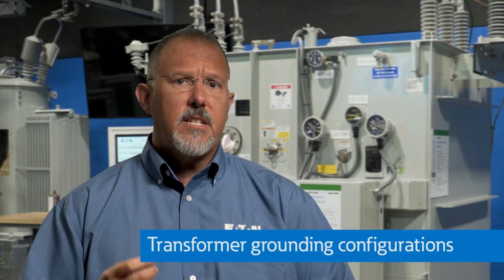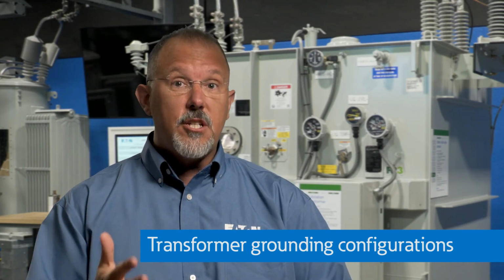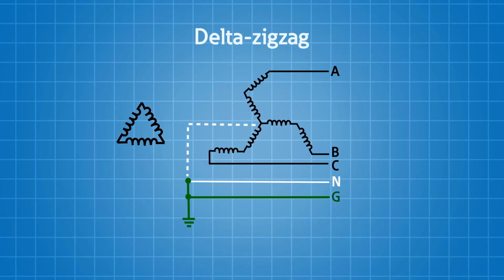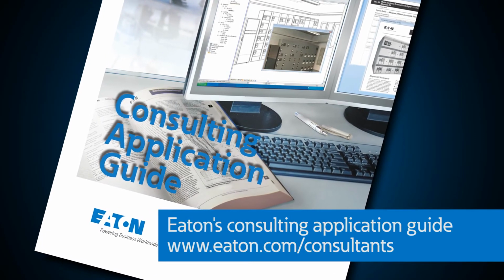The transformer is a very important piece of the power system puzzle because it establishes the voltage levels and that neutral point on the power distribution system. Depending upon the winding type, the transformer establishes the configuration that you will have to use. For example, the transformer connection may be a typical one like the delta-Y, or maybe more unusual like a delta zigzag or a high leg delta. Well-established methods for grounding and bonding these transformers can be found in our consulting application guide.